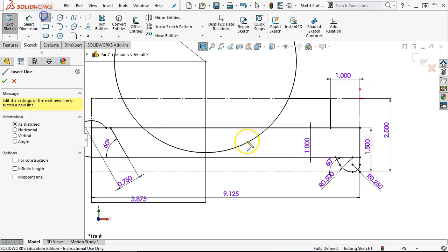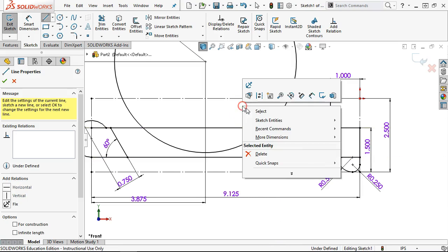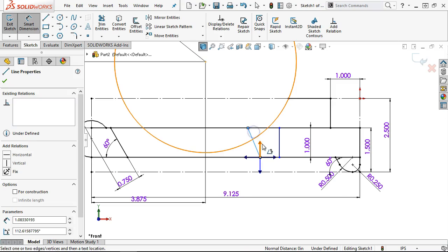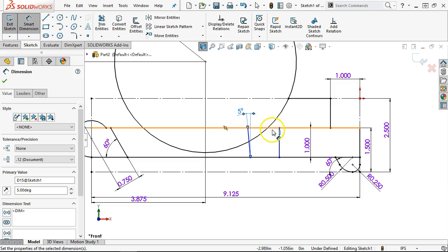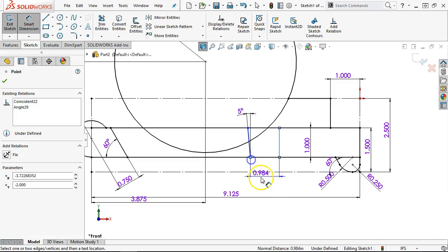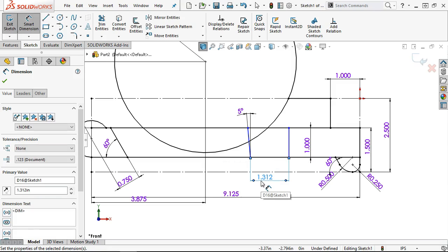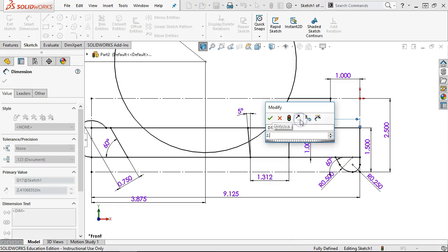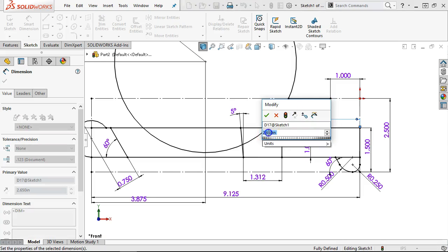Let's go ahead and put in one more piece of geometry, that notch out, and then the angle. The dimension for this one is 5 degrees off the base, so here's one of those places where I would use the arrows and go 5 degrees, and 1.312 on the length. And then its distance off of the end is 2.625. Oops.